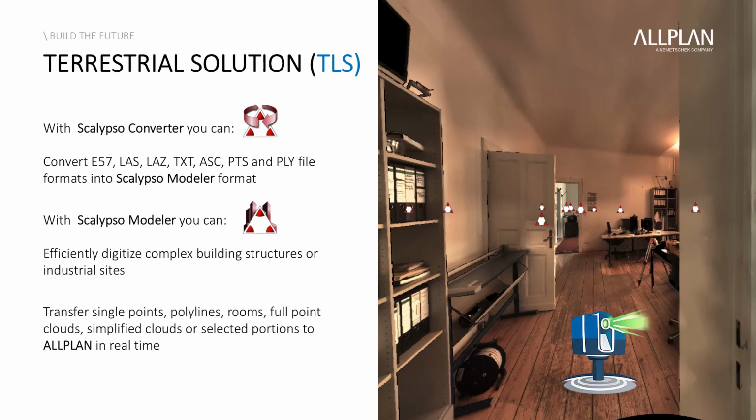I will have at my disposal a whole range of useful digital tools. For example, to take precise measurements, or I can choose to seamlessly transfer in real time individual points, polylines, or rooms. And by rooms, I mean the room entity available within Allplan, entire point clouds, simplified point clouds, or even single portions of point clouds.